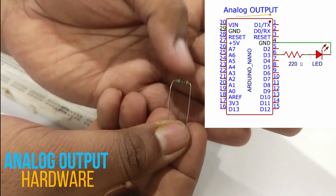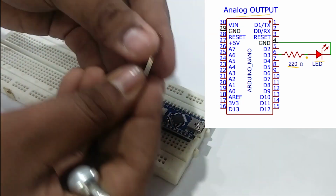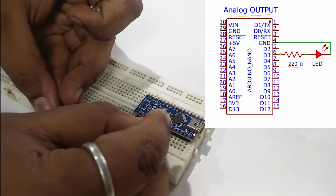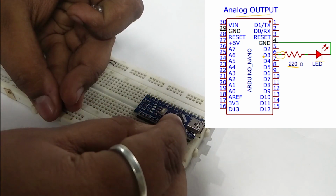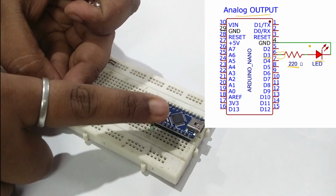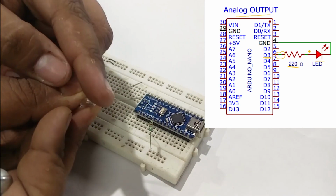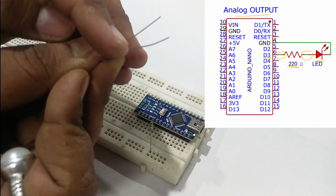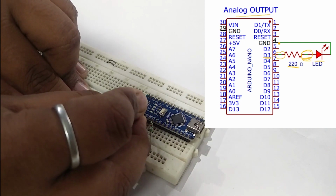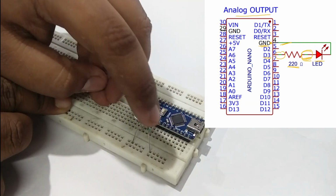So here we have this 220 ohm resistor and this LED. Now we will connect this LED and resistor to the breadboard. First I will connect the resistor to the D3 pin. I've connected one leg to this power rail. Now I will connect the positive of the LED, the leg which is bigger, the positive leg, to the resistor, and the negative leg directly to the Arduino ground. So we have completed our circuit.